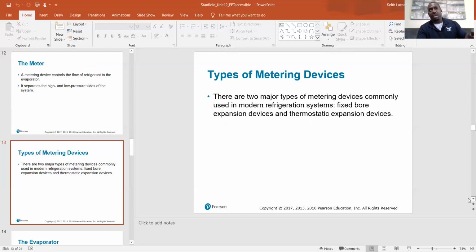If the suction line is not that warm and the refrigerant inside goes back to a liquid inside of the sensing bulb, then that vapor pressure is going to relieve off of the diaphragm inside of the TXV, and it's going to close a little bit. It's going to allow less liquid refrigerant. So anyway, I might have went too deep.